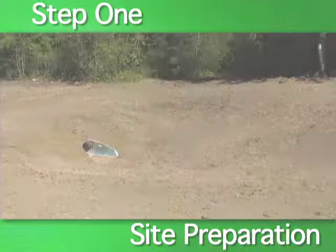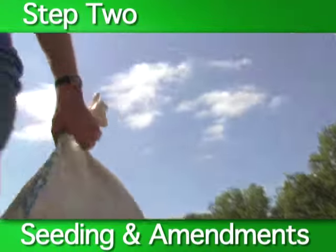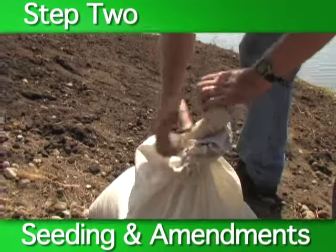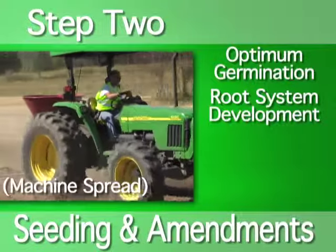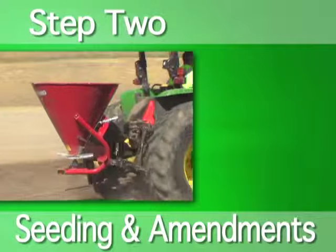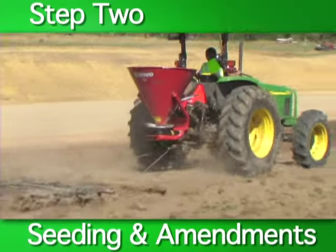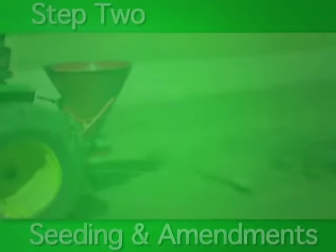Step 2. Seed and soil amendments. The next step is to seed the area. However, before applying seed, be sure to use proper soil amendment practices. Always match your seed to site soil conditions for optimum germination, root system development, vegetation density, and long-term functionality. Seed selection may also vary based on the water conditions expected immediately after installation.